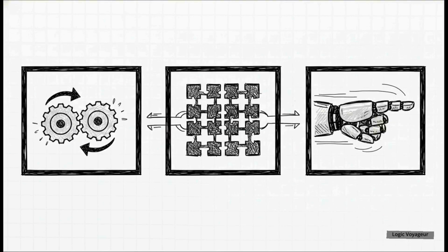Let's break down those variables really quickly. V is the velocity vector of the end effector, theta dot represents exactly how fast your joint motors are spinning, and bridging them together is J of theta, the configuration-dependent Jacobian matrix. Truly understanding this mapping is the ultimate secret to smooth, continuous, and safe motion on a factory floor.